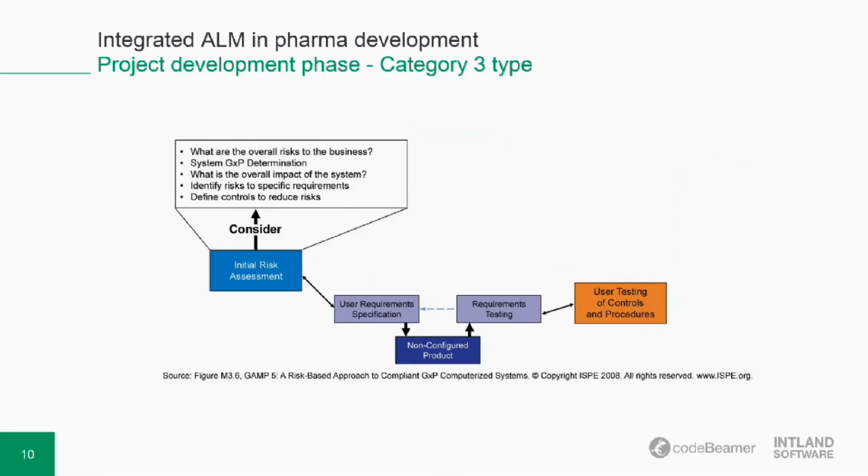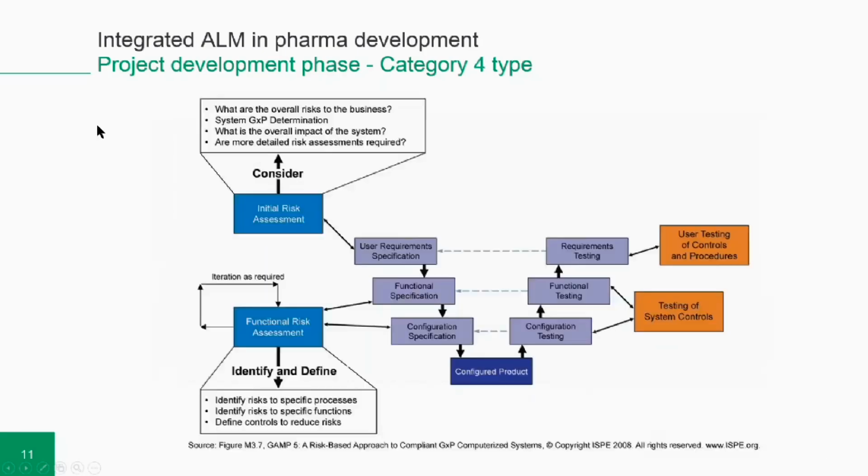To be able to understand this, we have to take the software models, what categories are included in GAMP. A lot of computerized systems, or a lot of parts of them, only have to be configured today and are ready to use. That's really a target in today's systems. In that case, user requirement specifications, which the user wrote based on an initial risk assessment, have to be satisfied by user acceptance tests. That's usually done by the user itself.